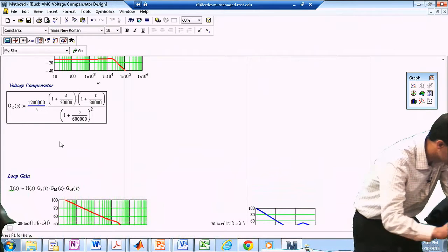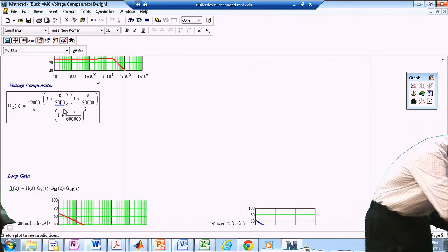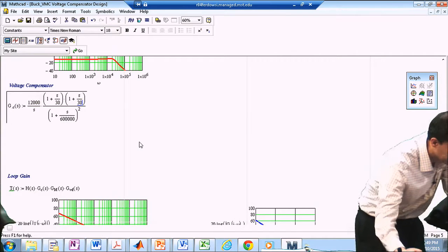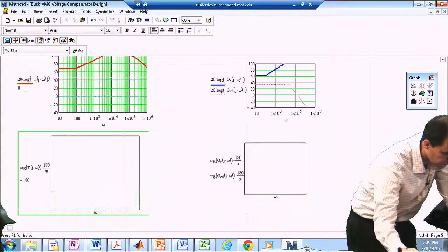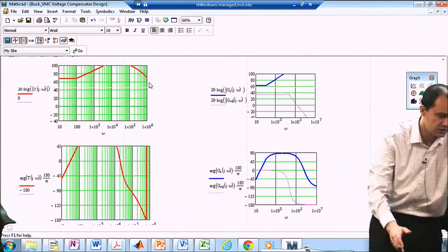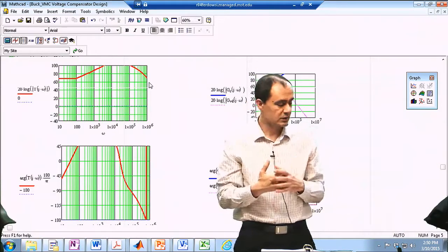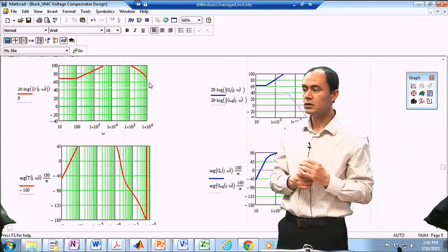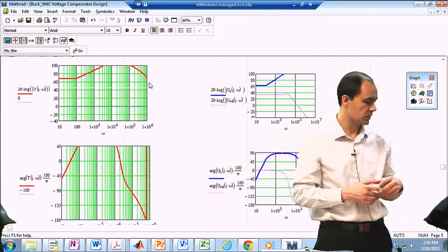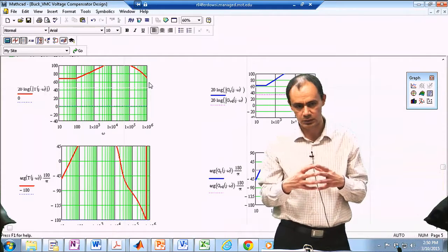we switch it back to 12,000. So as we saw earlier, instead of 30,000, if I just put very low frequency zeros, you get a very weird looking transfer function. And it is still stable, but as you can see, the system was very slow. So design is kind of an art. There's not one unique solution. It's just a matter of practice, trial and error. Look at the frequency domain response, look at the time domain response, and finally get to a particular point.